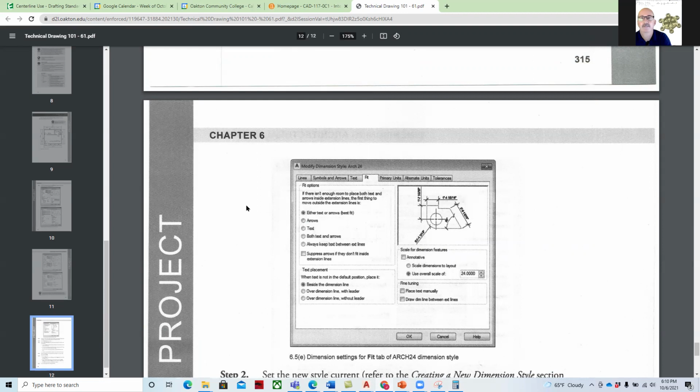When we're drawing in model space, this is an architectural drawing, so it's 18 feet by, I'm just going to say, 15 feet on the dimensions. We don't have paper that big. And so we use a viewport scale. And when we work with that viewport scale and set up our scale for that, we have this multiplier for calculating out the proper text heights.